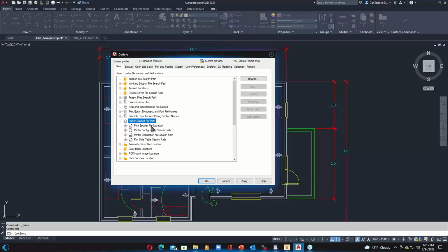I can configure all these different elements to streamline AutoCAD. So you're not having to deal with a list of different printers or plotters. Maybe you only have 3 plotters in-house. You only need those 3 plotters rather than a whole list of 20 standard plotter configurations and settings. So you can really narrow that down.